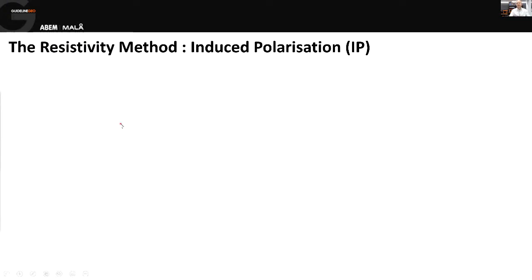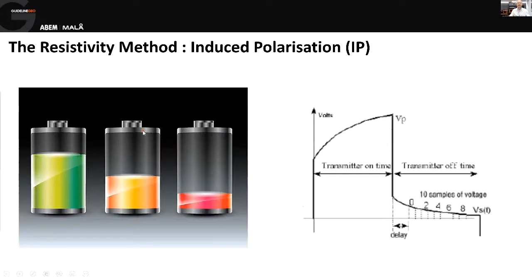Another thing that we can do is we can also collect chargeability data. So we can look at how the ground charges up when the current is switched on and discharges when the current is switched off. So this is something that can be very useful, especially in water and mineral surveys, this IP effect, induced polarization effect.